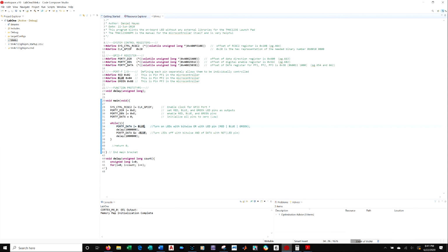have a blinking LED, and we do. So you can play around with the delay count number here. This number here seems to be about half a second on, half a second off. You can play around with that, but hopefully this video, maybe not so short now, can describe to you how the memory addresses work.